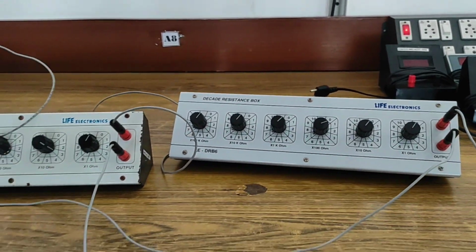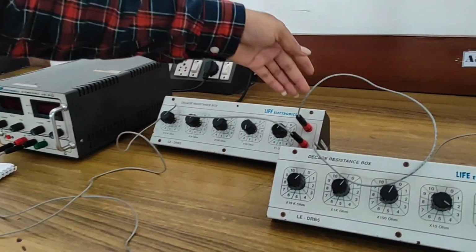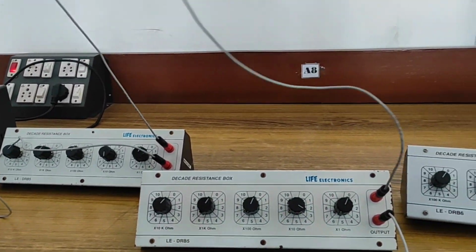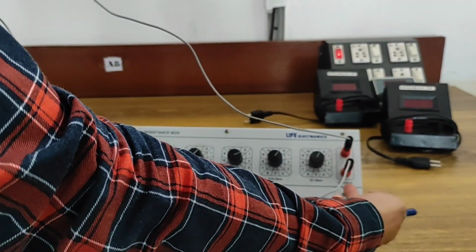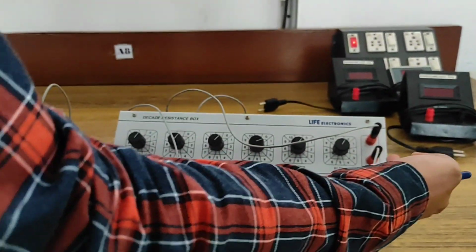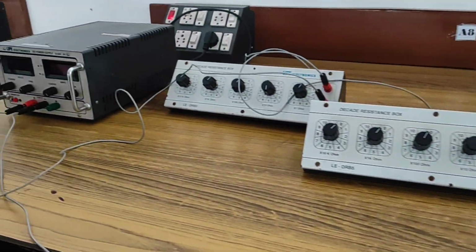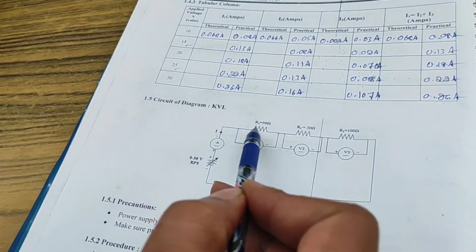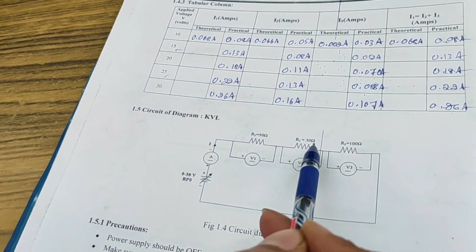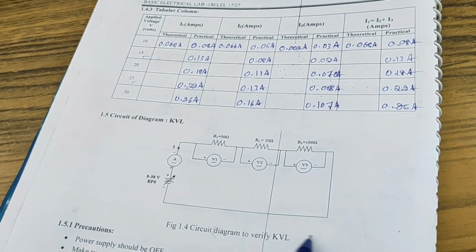In the series connection, the positive end is directly connected to resistance 1, and the other end of the resistance is connected to the next resistor, and the next resistance is connected to the third resistance, and finally the end terminal of resistance 3 will be connected back to the negative of the supply. That is what the circuit diagram shows. From the positive it is connected to R1, another end of R1 to R2, another end of R2 to R3, and the R3 end will be connected back to the